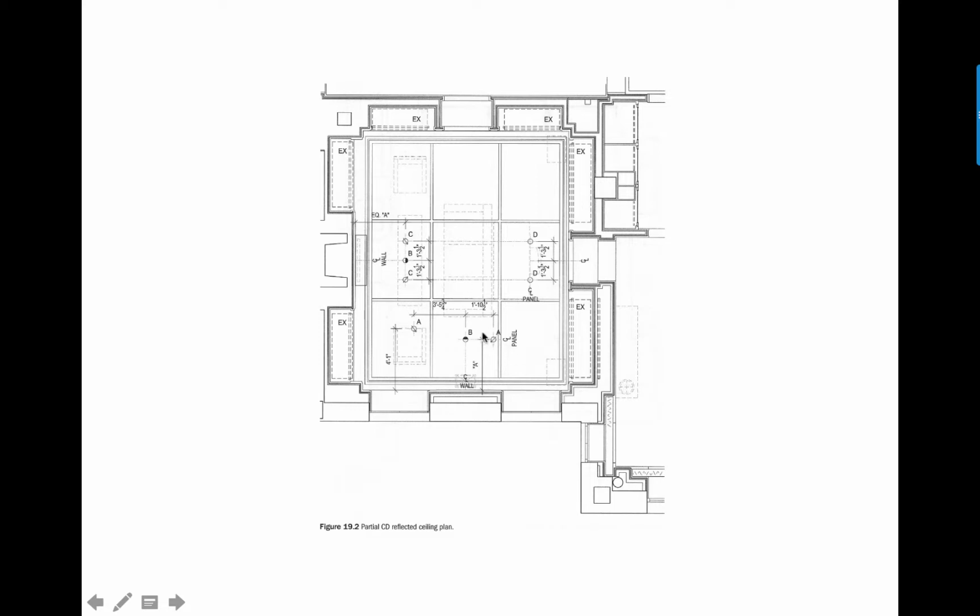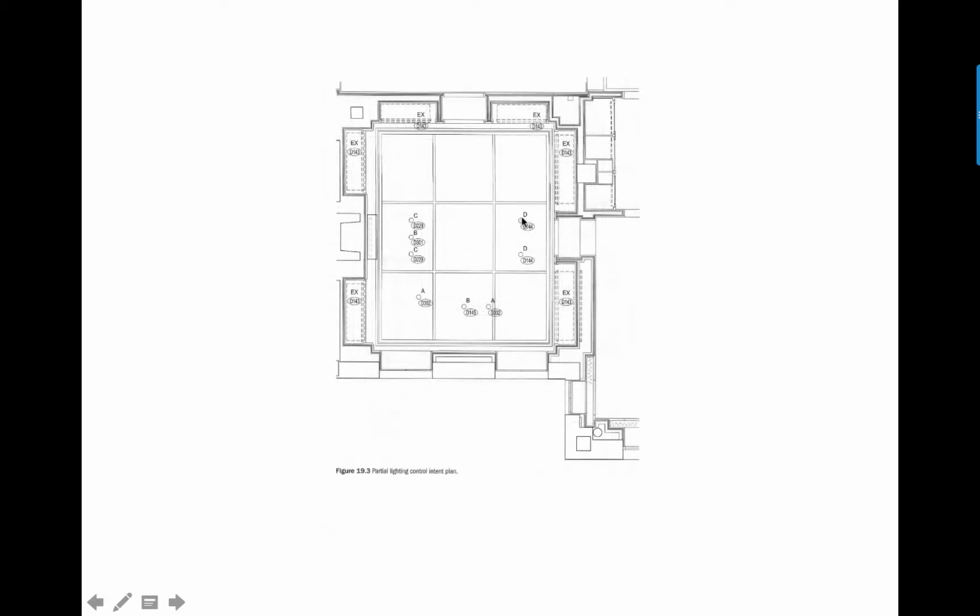Now, another dimension that is seen frequently is equal. So if you want something spaced equally between two objects, you'll put in that equal. I'm not sure where the other equal is. Anyway, every light fixture needs to be located in the room, off of both walls, both the left to right and the top to bottom direction.